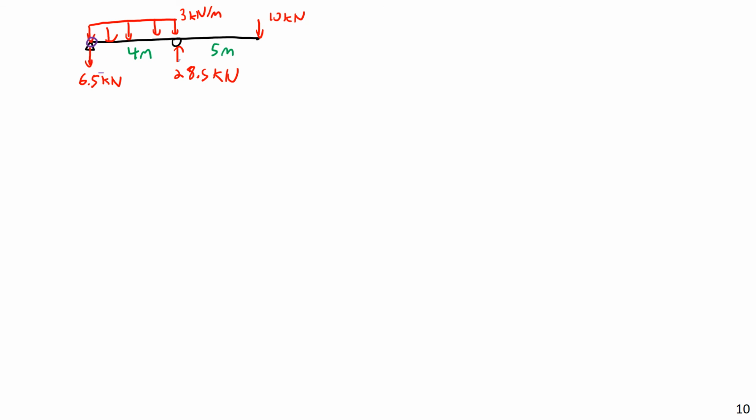And anytime you have a point force, or a couple, you are going to have a discontinuity. So I have one discontinuity here, from the reaction force, from the start of the beam, and from the start of this distributed load. Then here, I have a discontinuity from both the end of the distributed load and from the location of this reaction force. And then I have another one here, which is from the point load on the end, and also the end of the beam itself.